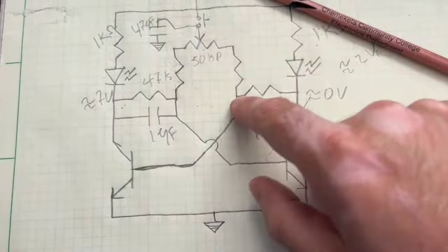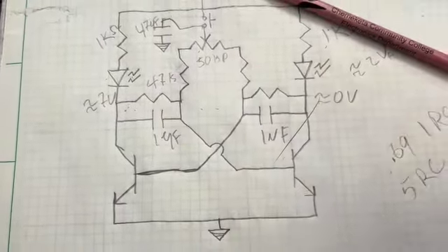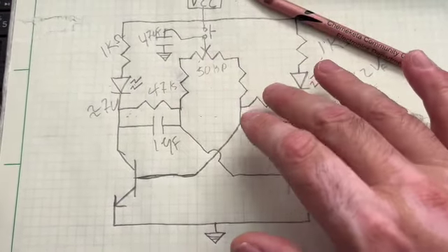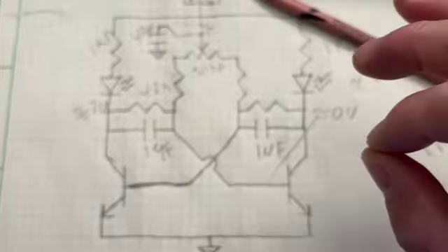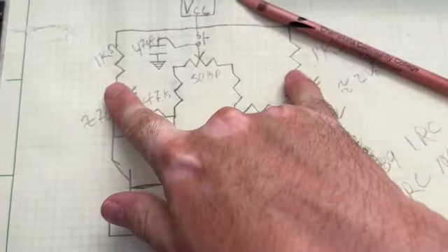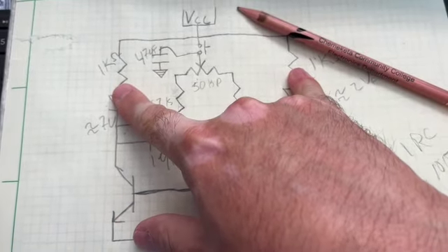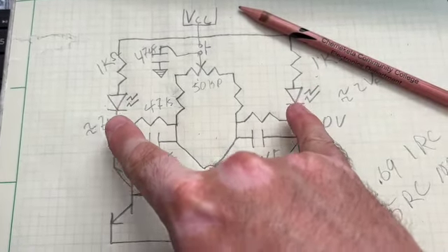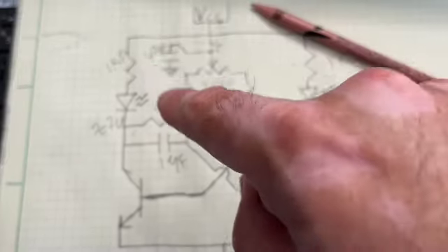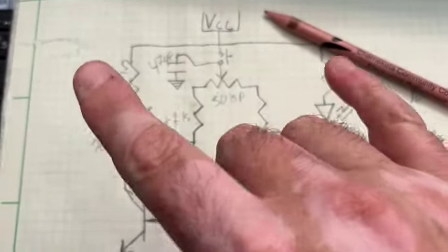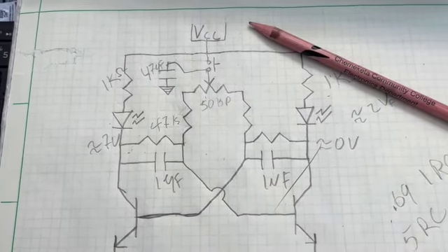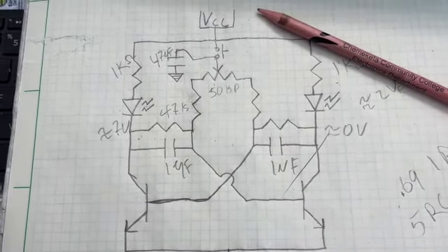Again, you can change the resistance values. You don't have to use any particular resistance values in here. It all depends on what frequency you're looking to create. As far as these resistors over here, these are current limiting resistors. So you just need to make sure that you have a proper current to be able to turn on your LEDs without burning them up. It's a current limiting resistance. That's all it is. And that, my friends, is how my favorite circuit works.